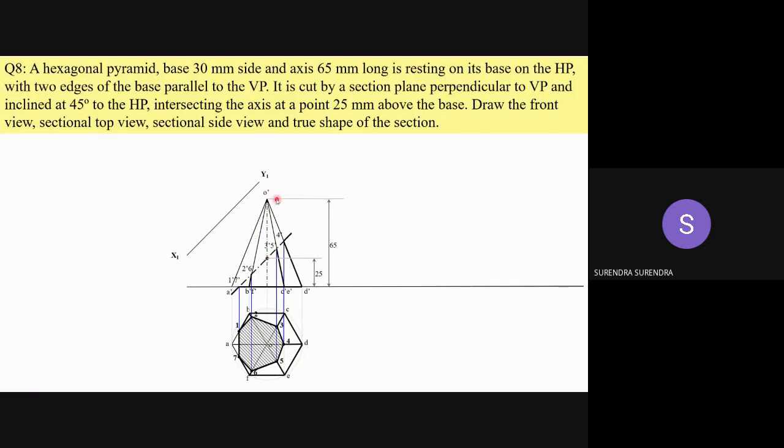To avoid that, what we will do is draw a line parallel to the section line. We draw one more line parallel to this sectional line. And then draw the projections, perpendicular lines, from each and every point. Each and every point, draw perpendicular lines, and here what you have to follow is measure the distance from the XY line to 1.